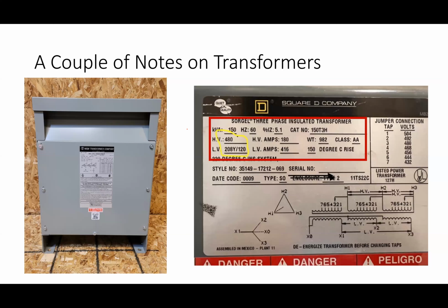Now you don't touch the core itself. What I have there is an outer shell, and notice along the top here, I've got a vent for air to pass into it. The key thing is that the transformer is going to get hot. The core is getting hot. It's also the case that the windings are going to get hot.